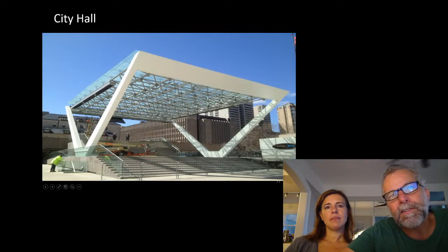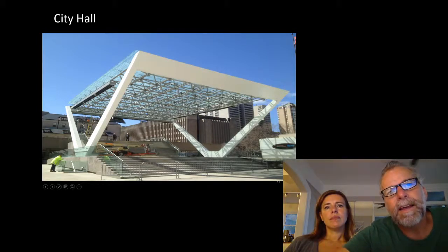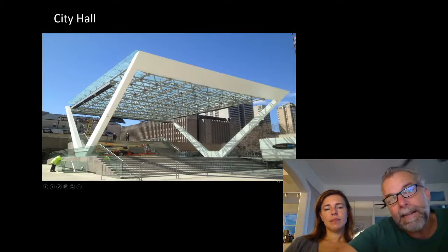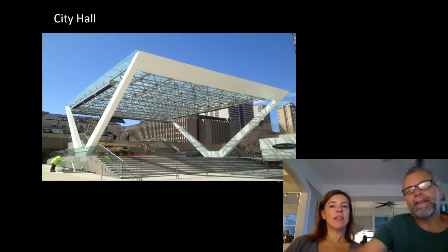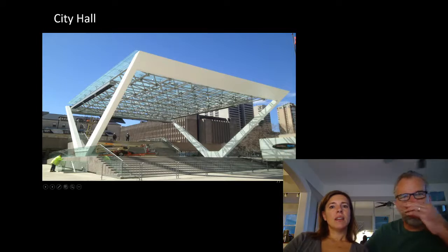In this direction, they don't cantilever up. We don't have base fixity here. In this direction, it's a very traditional moment resisting steel frame. So you can see you get your fixity from this big beam element at the top. And then in the end, of course, architecturally, the effect is one big long ribbon, right? It's one continuous member. But I thought that was really a clever solution to have the two different